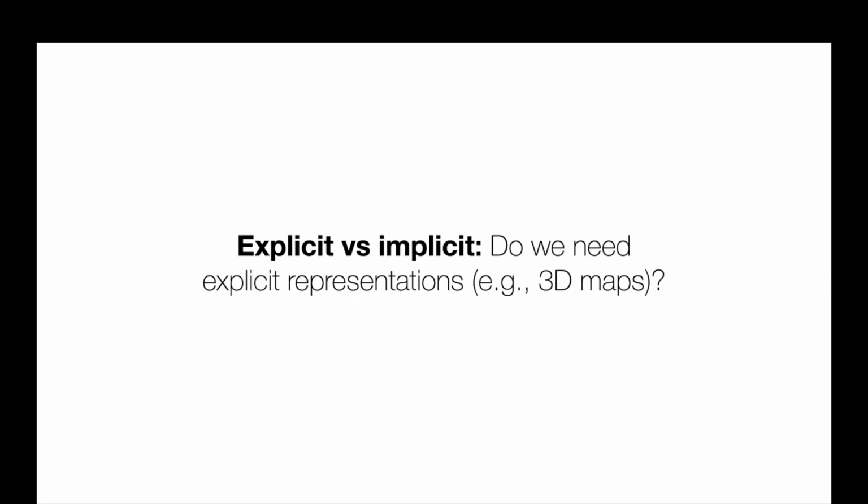If I can add on top of that, there is also a trade-off in terms of sample efficiency. I'm thinking about reinforcement learning. If you have to do the reinforcement learning from scratch, like pixel to action, you will need many samples, many trials, because you will need to figure out the perception part. The internal representation, we'll have to figure it out from pixels. Instead, I think there are a bunch of papers in which, if you feed to the reinforcement learning some intermediate representation, call it maps, or call it some intermediate representation, you can get way more sample efficiency, because the reinforcement learning will focus on the control part of the task rather than the perception one.